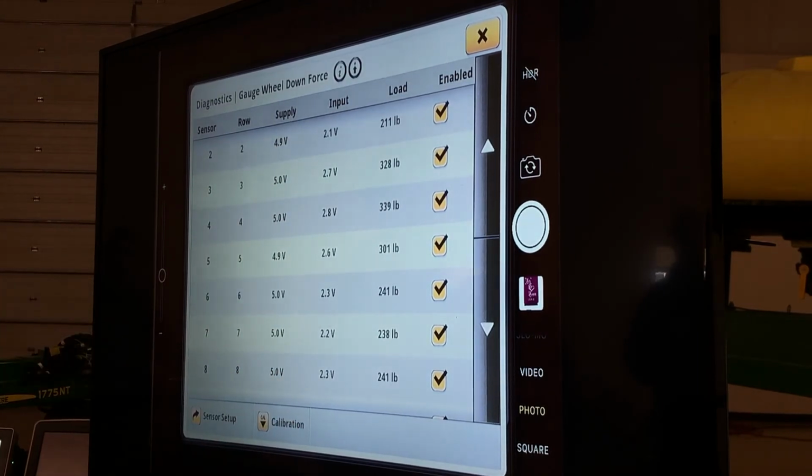On our old pneumatic systems, we used to have a sensor that goes bad, and I could just disable it because it's taking an average. On these hydraulic systems, I discourage that because every row is different. It no longer is taking an average. And so at that point, if you disable that row, it's just hanging out, not really knowing what to do, so your performance is affected.